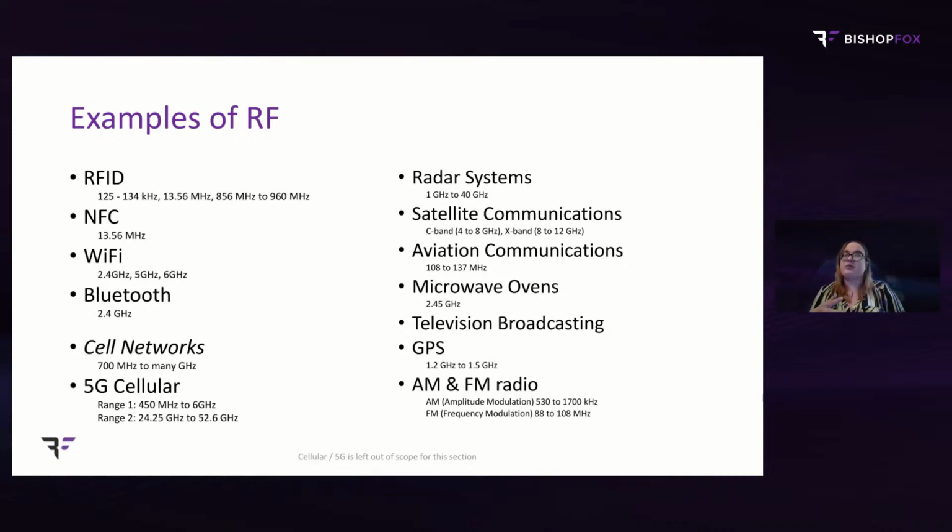And this is actually why 2.4 gigahertz Wi-Fi has a longer range than 5 gigahertz Wi-Fi before signal is lost. And again, that does have to do with the assumption that they have the same power associated. Obviously, if the powers are different, then you'll get different signal strength.